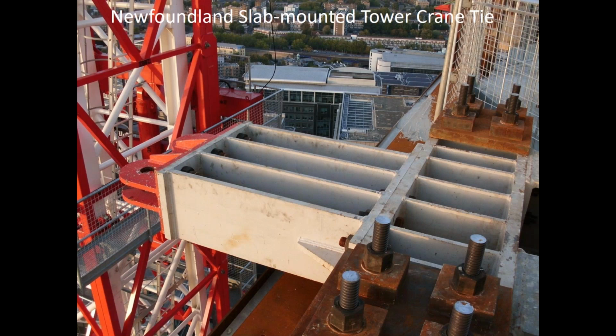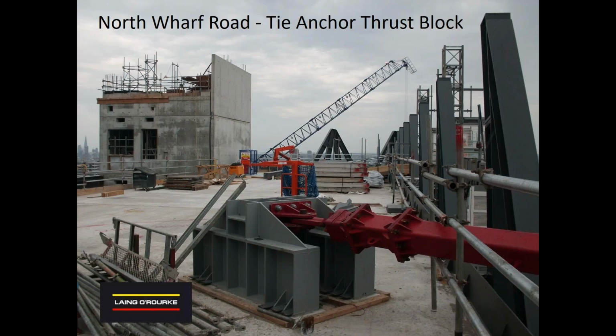Here, in this photo, we're waiting for the ties to arrive to attach the thrust block to the mast so that the ties can do their job and restrain the tower crane mast. There are similar details at Norfolk Road. Again, heavy eye sections, stiffeners, bolts into the concrete slab, preloaded to set values.